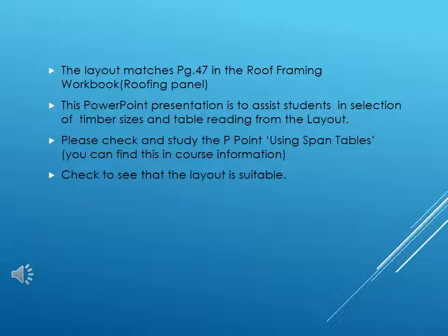To understand everything about using span tables, I strongly suggest that you study the PowerPoint using span tables, and you can find that within the course information. This is absolutely essential before you start working out figures. The fourth point is when you actually have a look at these plans, check and see that the layout is suitable.